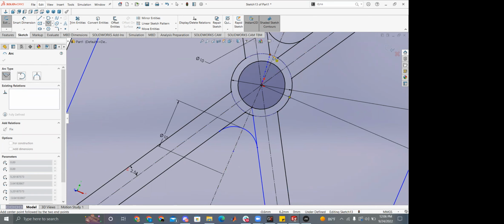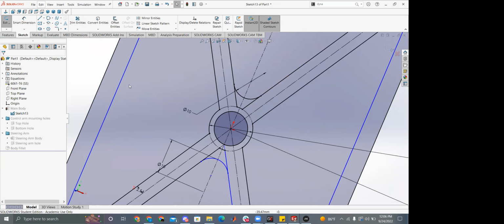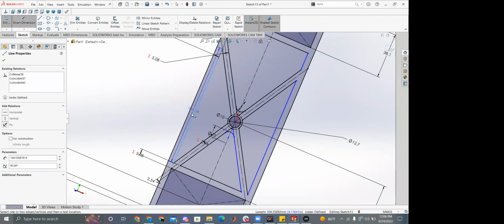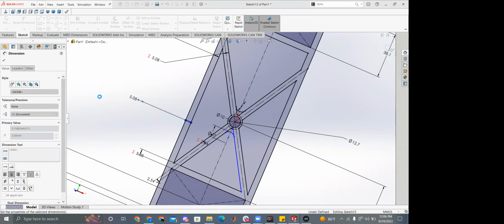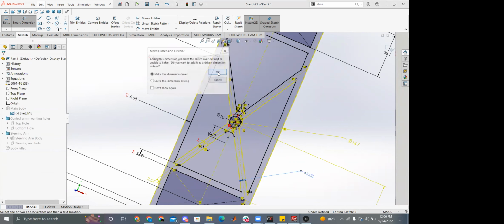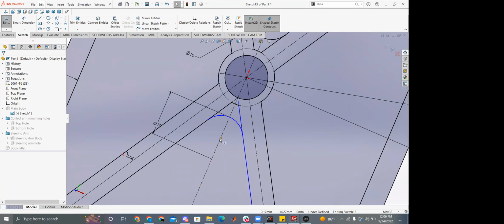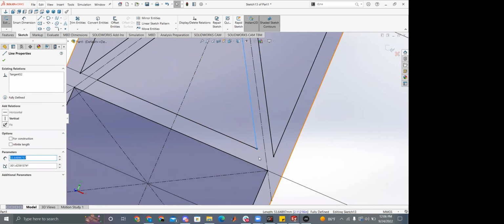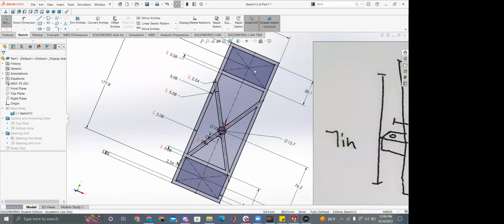So we've made that construction geometry and we're using it as a template. Kind of just draw some minor arcs to cover it up. You can see those are all blue. A lot of these are no longer blue because we lost a relation. So we can simply do it again. Okay. What's wrong? Oh, right. Okay. So now we've cut out those lines.